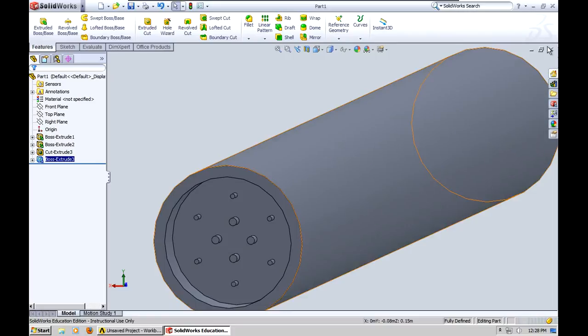This is going to speed up the processing time in a way, because I won't get an error for the outlet, because I'm going to make that face over there the outlet, like a pressure outlet, probably not an outflow, but I'll make it a pressure outlet, and this is going to be a super turbulent area.